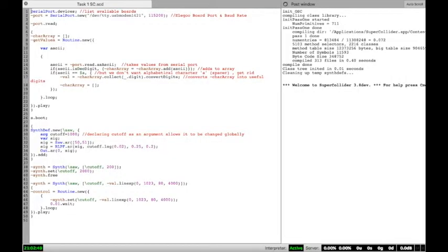So inside Supercollider, with the Arduino IDE shut. So this is the code which I've developed for the transfer of the file data through the serial port. So up here is just the standard serial port detection, and this basically just tells the user which devices are available, and then this one just selects the port used for the USB data flow. So I've got it set to USB modem 1421. This may change depending on which USB port you're using. And the baud rate is set to 115,200.